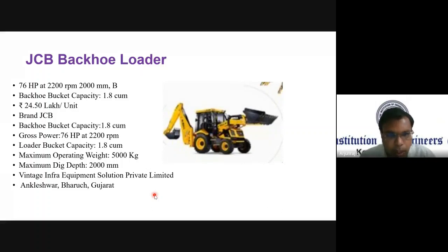This is the JCB Backhoe Loader. You have a cubic meter capacity of 1.8. It's slightly higher than others. Like we have seen 0.6 and 1, but here the backhoe bucket capacity is 1.8 cubic meter, and accordingly the cost is slightly higher because the bucket size is higher. So unlike what we have seen, 18 or 22, now here it is 24.5. Because again the corresponding cost increases because of the size increase.